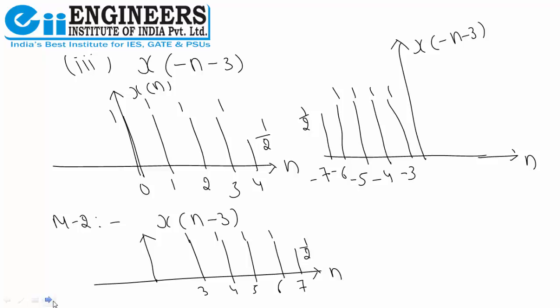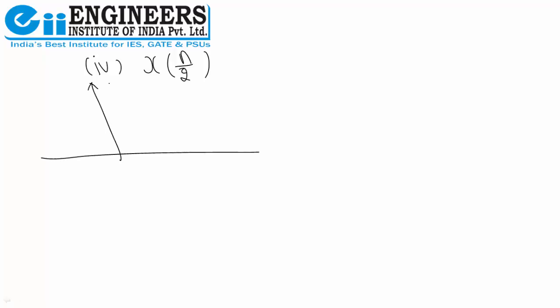Now suppose you want to understand the scaling operation, the decimation and interpolation concept which I told you about. For that, I want to perform x[n/2], and I will again take the same x[n]. Now you will be able to understand what the decimation phenomenon and the interpolation phenomenon are. Again I will take only the 5 samples.